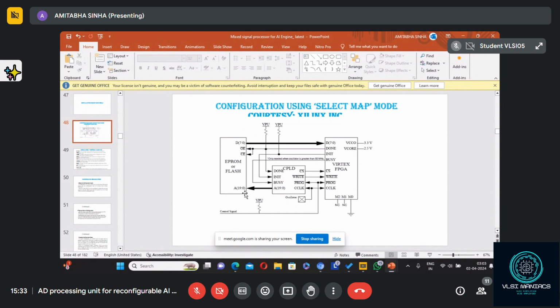On the left-hand side of the CPLD, what are the signals? Address lines are connected directly to the flash memory, and the data bus goes directly from the flash memory to the FPGA. Then the down signal. Each time, the down signal goes low when the data is not yet downloaded. Once it is low, OE bar is low and CE bar is low, then the PROM will be selected. Depending on the address given by the CPLD, the data in that address will be downloaded.